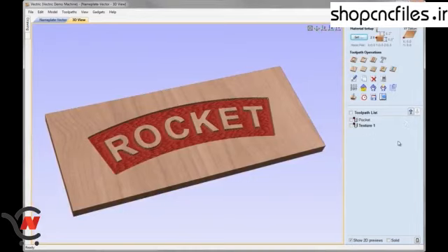So there I've just closed the preview menu again to come back to the standard toolpath tab and come into an ISO view in the 3D view by clicking on this icon here. Now we're going to go to the 2D view again and select our holes to create our drilling toolpath.